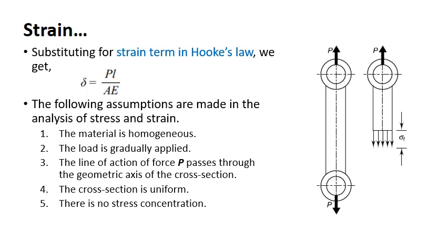So this is where Saint-Venant's principle becomes relevant. Okay, so we have to apply Saint-Venant's principle and measure the stress 2 or 3 times the characteristic length, that is the smallest characteristic length of the specimen, from the point of application of the load. If it is a circular one, 2 or 3 times the diameter. Far from the point of application of the load, we have to measure the stress, because usually you will have no stress concentration at that point.